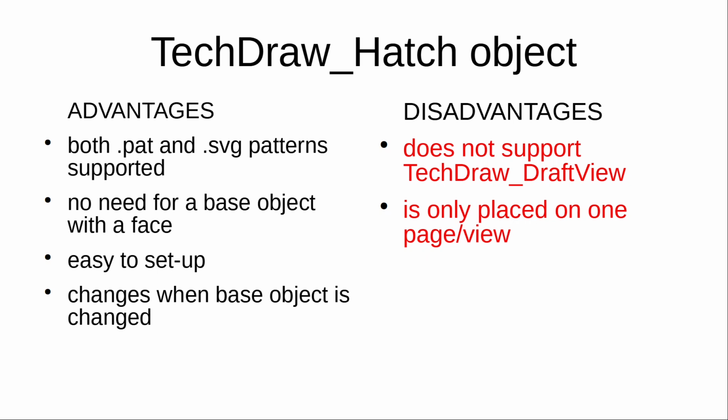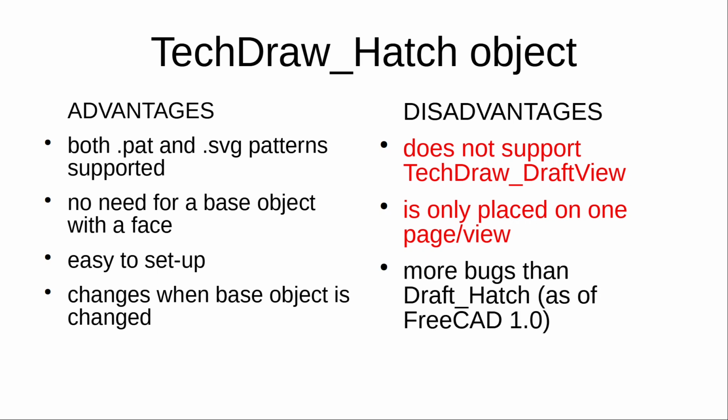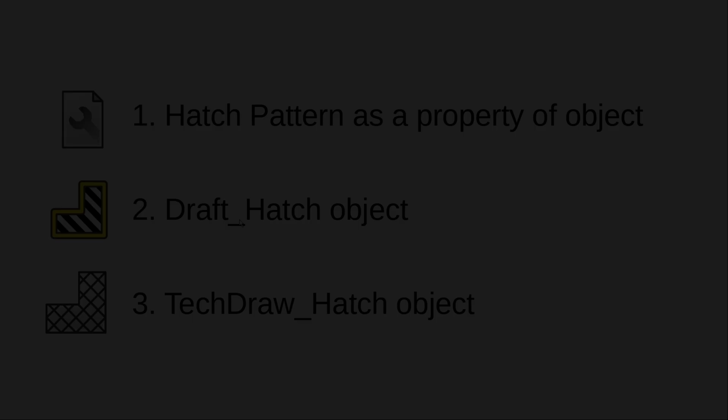So if you want to have the hatch on multiple pages, you have to create it multiple times. And again, I think it has a bit more bugs than the draft hatch as of FreeCAD version 1.0. Sometimes when you rotate the hatch pattern, it doesn't really work as expected.